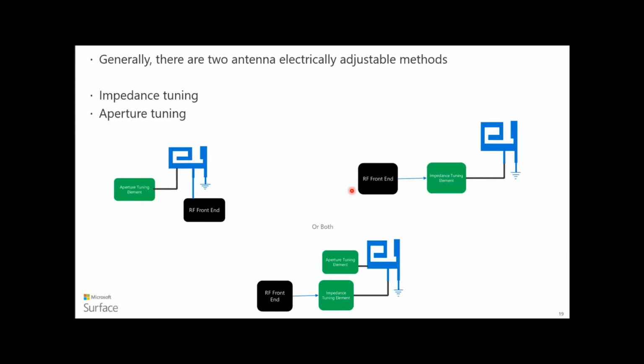The other way of doing it is this: one of the problems with the antenna getting smaller is that the impedance bandwidth can't be matched to 50 ohms across all frequencies. So another method is using a similar concept but for impedance matching.